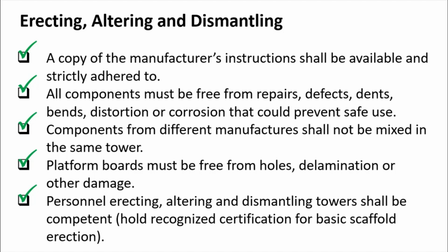Of course, you need to provide competent supervision as well, to check the progress of works and whether the work is being done correctly. If the person is competent to do the job, they can immediately recognize the unsafe practice, the unsafe parts of the scaffolding, or the unsafe condition of the area before they start, so they can make rectification before continuing.